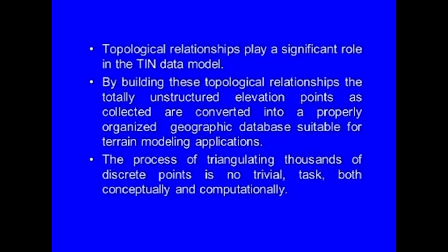By building these topological relationships, the totally unstructured elevation points as collected are converted into a properly organized geographic database suitable for terrain modeling applications. The process of triangulating thousands of discrete points is no trivial task, both conceptually and computationally.